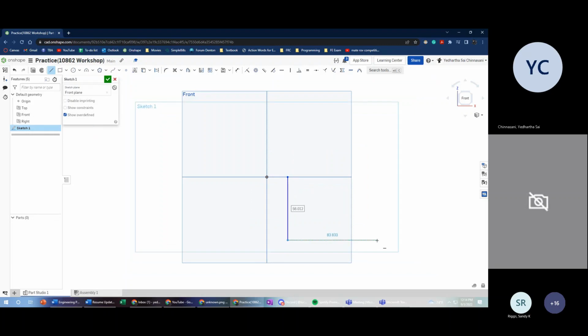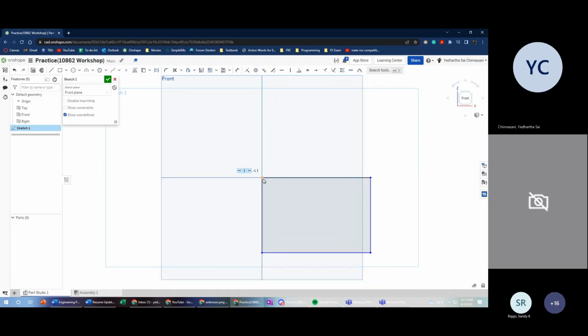Because when you draw a square out in the middle of nowhere, the CAD system doesn't know that the square is at a certain point. It basically recognizes it as a free floating entity, and it will cause you some errors when you have multiple complex shapes if you don't have it touch the origin. So whenever you start, make sure you're always intersecting with the origin.